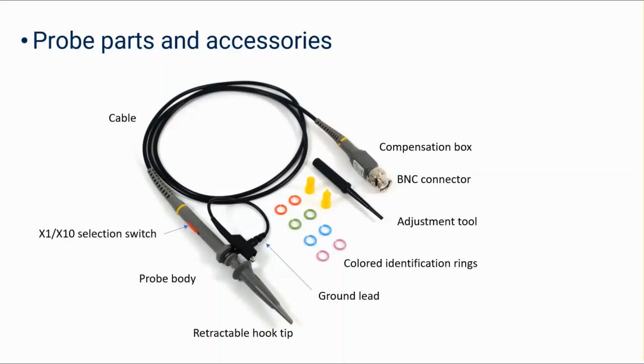So that can be very useful in itself, but the ×10 probes also address another problem. With ×1 probes, the circuit under test is directly exposed to the input capacitance of the scope and also the capacitances in the probe cable, which loads the signal at higher frequencies and may even stop the device from operating properly.